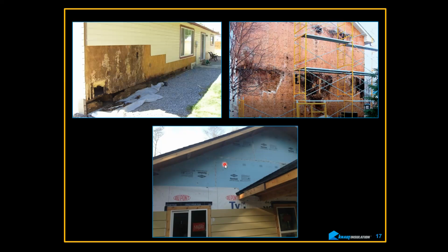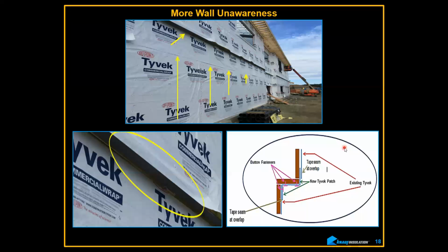It's very impermeable. So as we move out an assembly, we want the permeability of each layer as you're moving out to be a little bit more open than the layer behind it. Okay, so you do have ways to get rid of that moisture. In other words, think of a funnel pointing out with the opening of the funnel, not the tailpiece that goes in the bottle, pointing out. That's kind of the graphic that you want to look like, where the outermost part is the most permeable and then the least permeable on the inside, or the sheathing, let's say OSB, as an example.